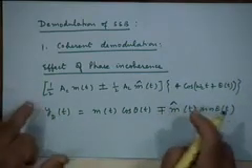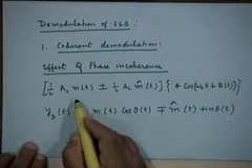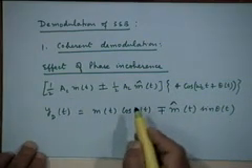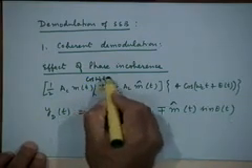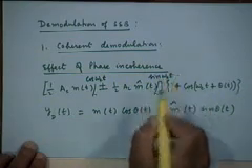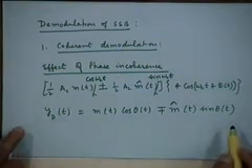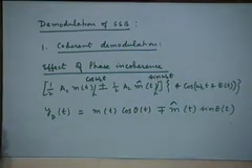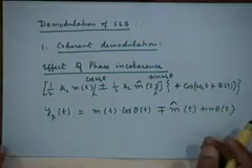When you multiply these two, oh, there's something missing here. No one has pointed out. This should be here. There is a cosine omega_c t here, and there is a sine omega_c t here. So you're multiplying these two, removing the 2 omega_c terms, and seeing what is left. This is what you will have.